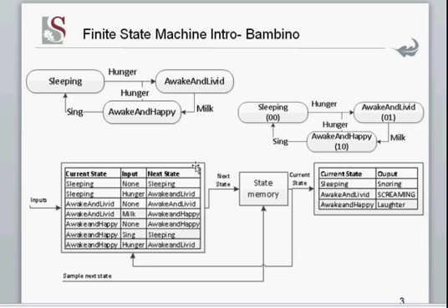So what you will see is this input block, what we call the next state logic, that determines what the next state should be. That's just going to be normal AND gates, OR gates, and NOT gates, just normal combinational logic. On the output side, again, this block that determines what the output will be is just combinational logic. However, the middle part is the part that remembers what the present state is. It's like the inertia of any system in the real world. It remembers what state you're in.